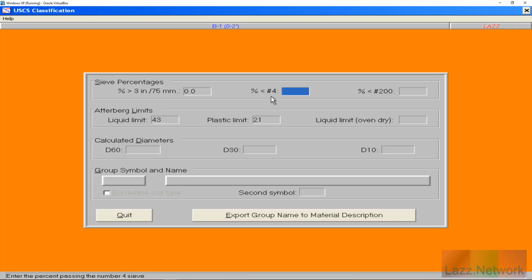You can buy sheets and rolls of this stuff, which is usually for big aggregate processing plants for asphalt and concrete to get mixed designs and things together. So it's not about how big the sieve is, it's how big the openings in the sieve are that matters the most to determine your particle size.